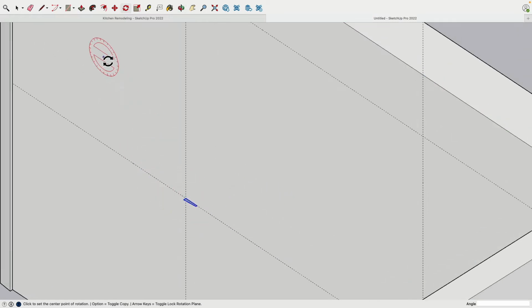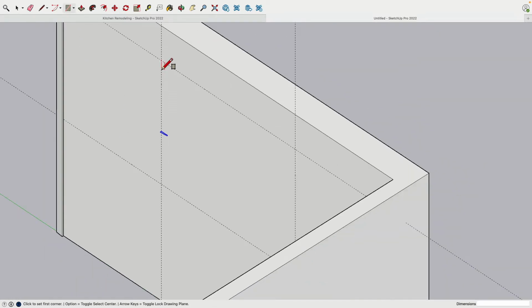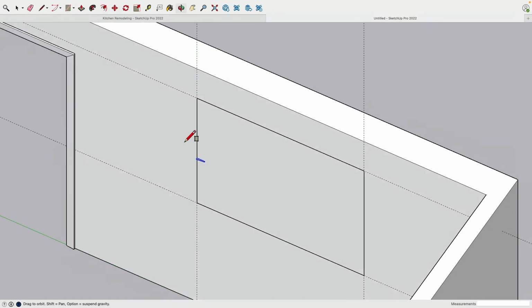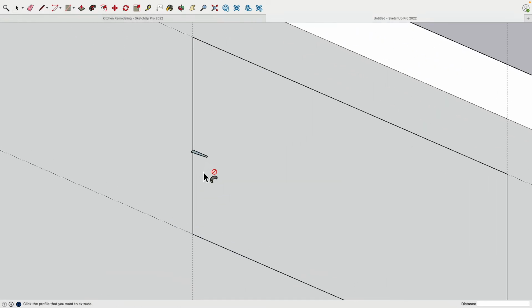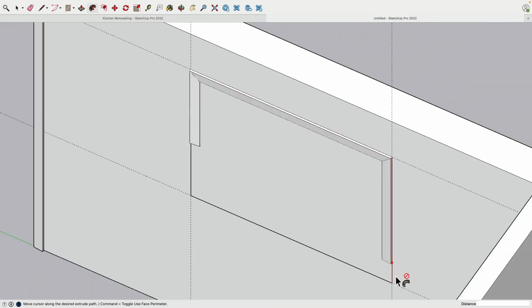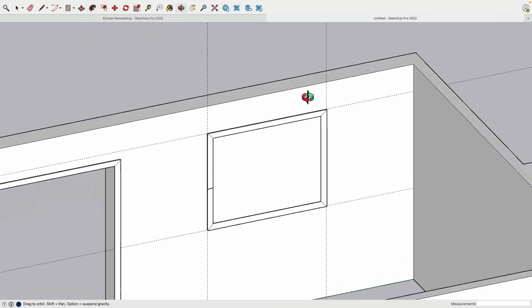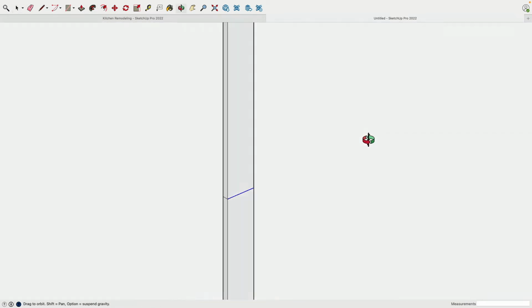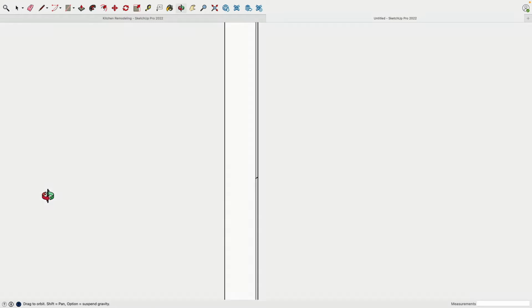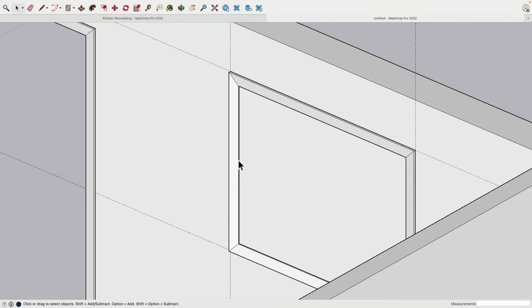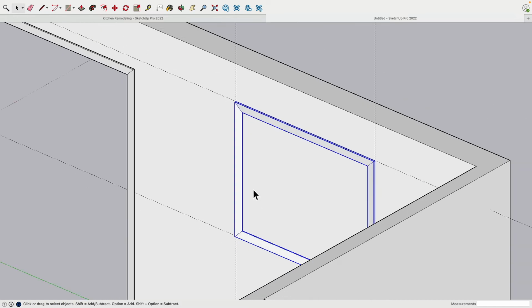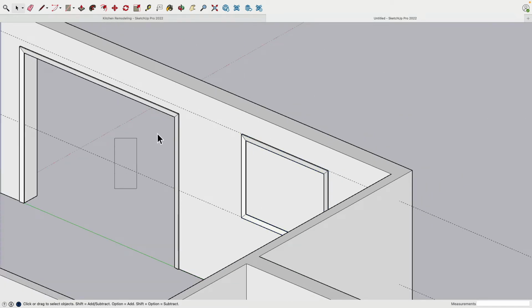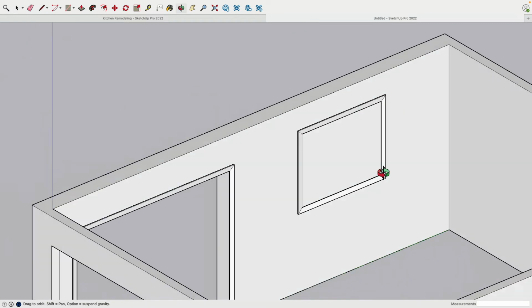Now this is at the end, not necessarily very good, so I move this one up a little bit. Yeah, then let's draw our rectangle. The face we can remove, and then with the follow me, there we are. And do a little bit of cleanup here. There we are. Select everything, make group, and then all the stuff I don't need, guidelines are gone.